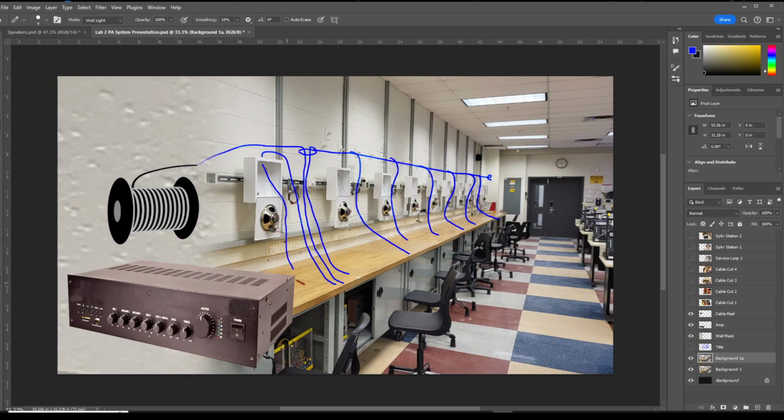Run it about that, because you're going to have to provide for a little bit of stripping of the wire, peeling the jacketing and all that stuff. You need to have some length, comfort. So comfort of length. All right. So then after the whole thing is cut and stripped, we're going to make a pigtail, joining it.